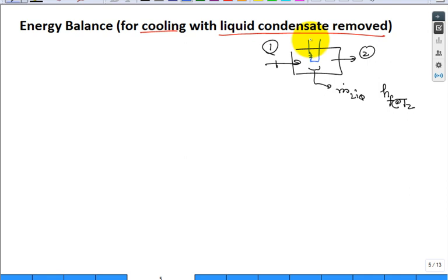But anyway, from the perspective of the energy for the moist air, there's a Q dot, get rid of this red line there, Q dot going out. Going out of what? Going out of the moist air stream. Where is it going? Either into the refrigerant that's inside the coil or the water that's inside the coil, but it's going out. Makes sense?